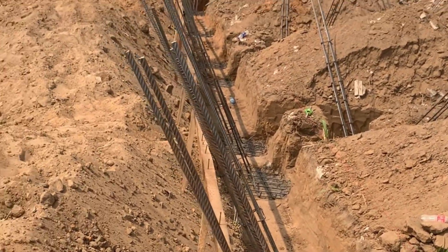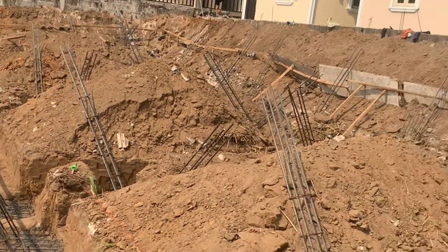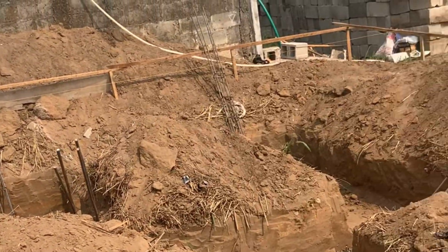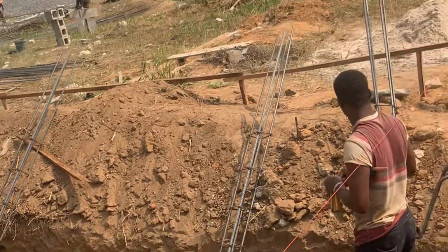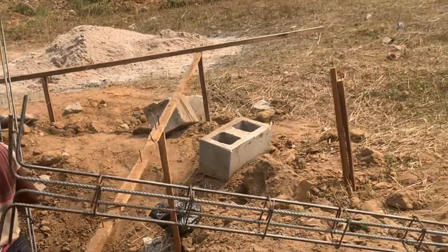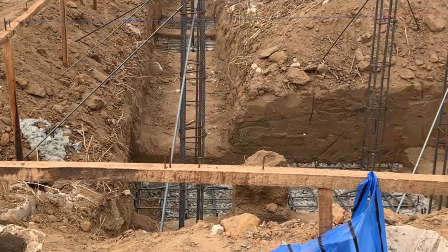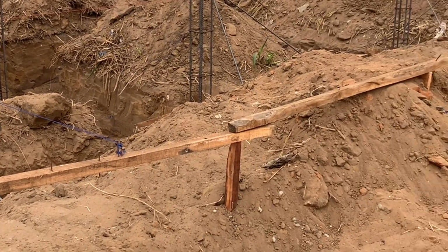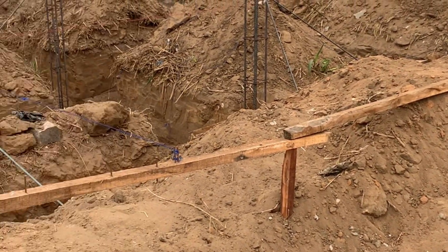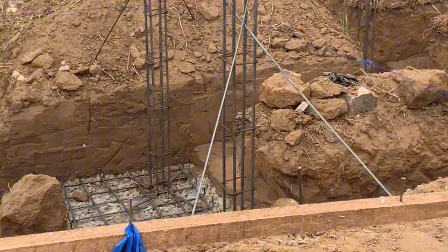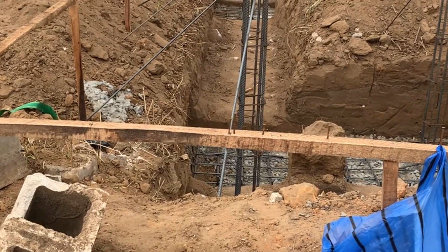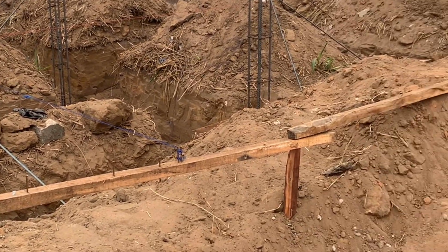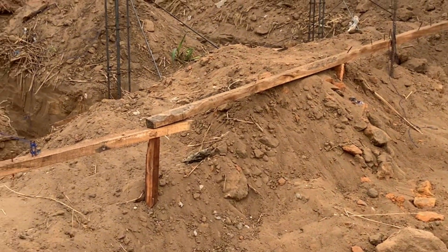This stage requires preparation of reinforcement to meet up with the design detail. Once the reinforcement baskets and columns have been prepared to detailing, make sure during the placement of the basket to the column base, the surface area is free from any red mud. You can as well use water to flush away any sand to keep the surface clean. One more thing, during that erection of the column to the basket, please make sure that all the columns are perpendicular to the foundation trench and in line with each other. Okay, take note of that.